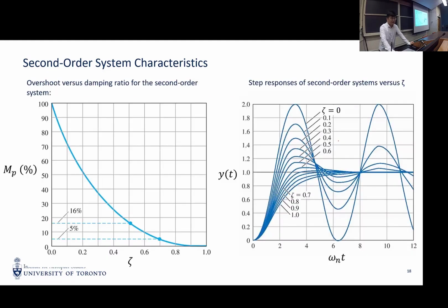This is a diagram of the effect of different magnitudes of zeta and omega. Usually from 0.7, this is a desired response. So we should pick zeta around 0.7, such that our system will be steady with no very aggressive overshoot.